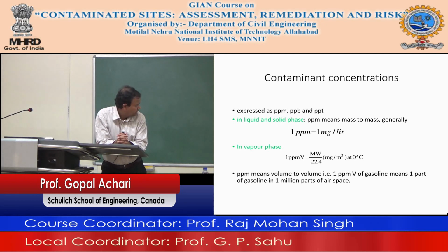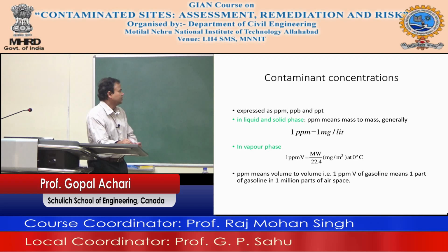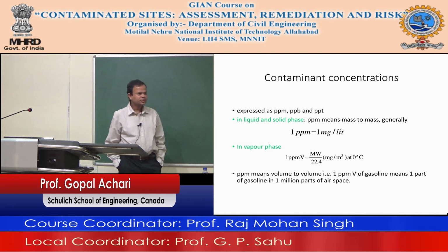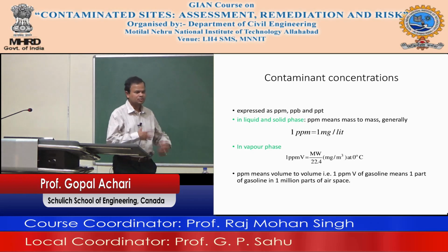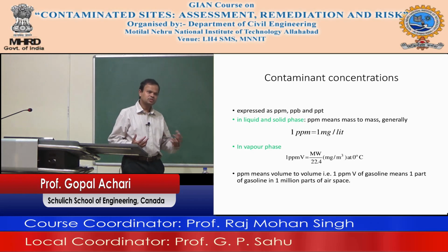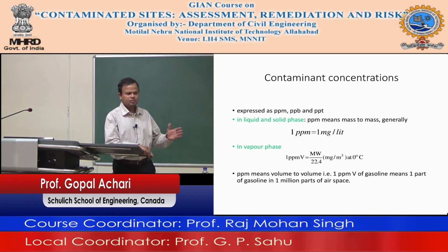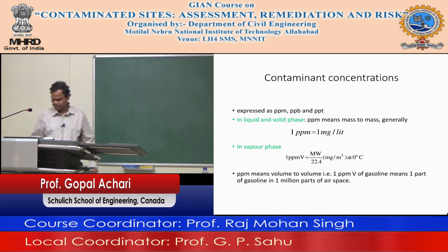Okay. The process itself, preparation of site specifications and site plan specifications, you have to have a monitoring and sampling plan. How are you going to sample the site? What kind of method will you use? Will you use judgmental sampling? Will you use grid sampling? There are different ways of sampling. You have to factor all that in.